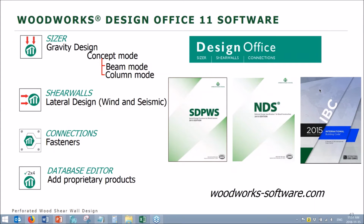The first module is the Sizer module, and Sizer does gravity design. So it can design single elements within beam mode. We can design beams and joists. Within column mode, design columns as well as stud walls. And additionally, within Sizer, we have the concept mode, whereby you can lay out an entire structure, the columns, walls, the beams, apply the gravity loads, and the software will automatically run the loads down the structure and design all the individual elements.